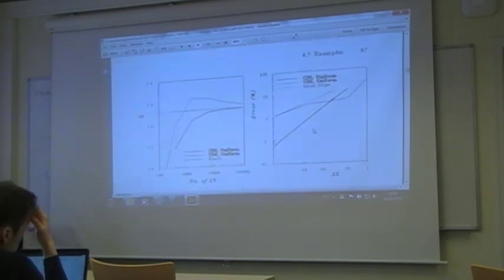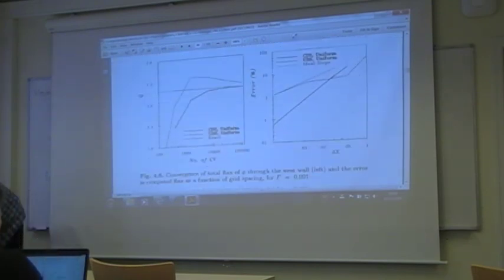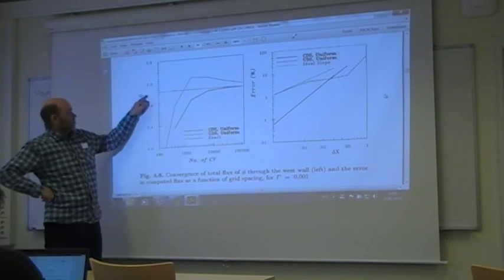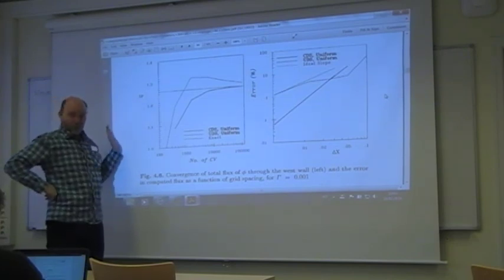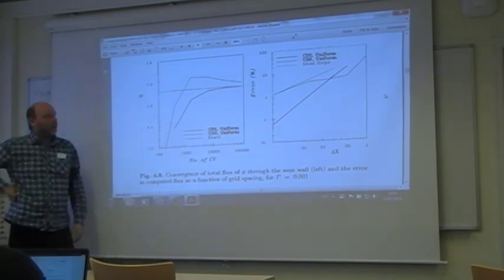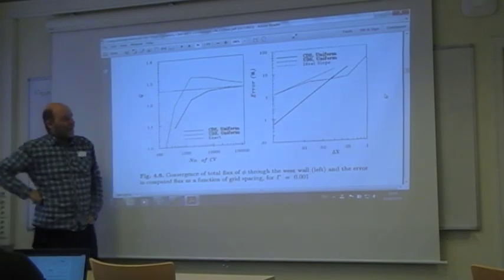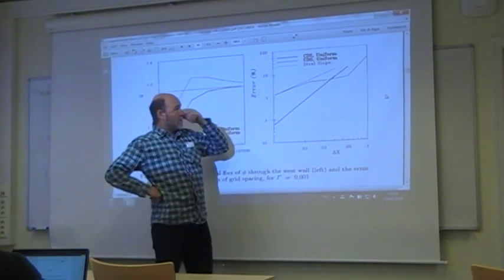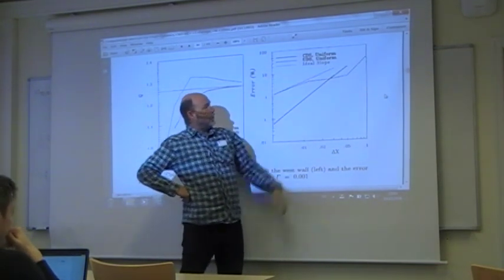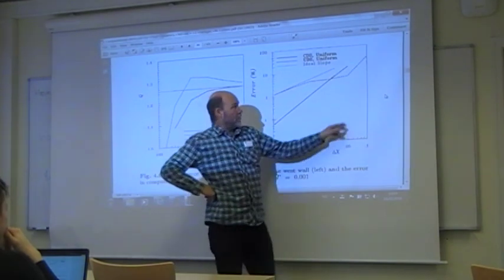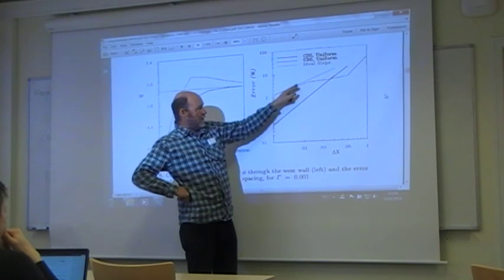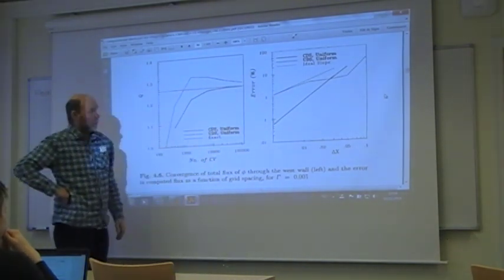And again here as a conclusion, when you look at the error, you can sort of look at the transport of whatever should be diffused through the y-axis. You have the second order slope for the CDS scheme, for the upwind scheme. Well, for coarse meshes, it's rather strange behavior, but finally it will settle down to the first order accuracy slope.